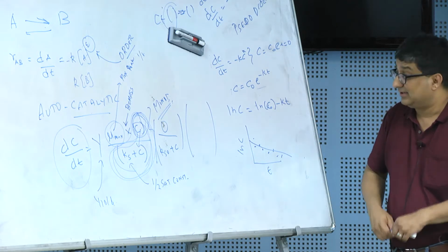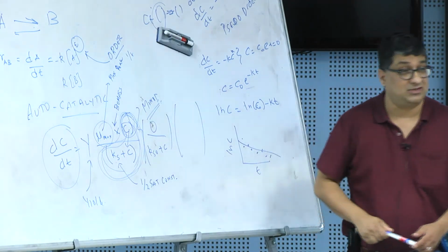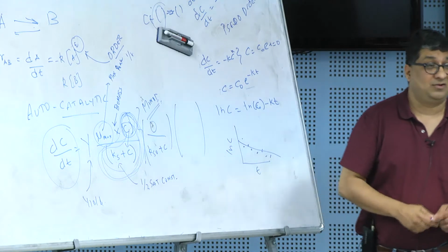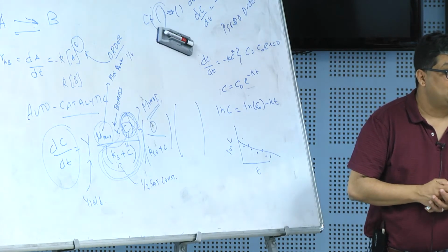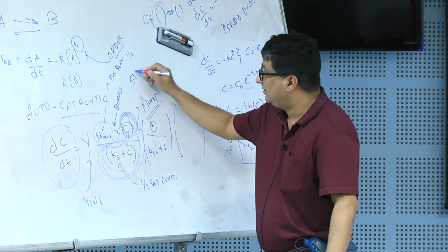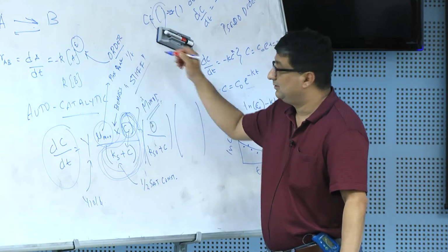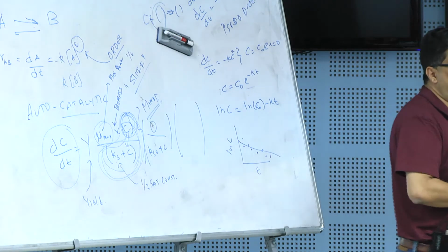The downside of it is there is concentration here, there is concentration here if we want to solve for concentration, so it's a highly nonlinear equation. And this is one of those equations that are called stiff equations. Okay. So when I was talking about differential equations, you see these big transients for certain concentration ranges. Suddenly the model starts to go crazy. Okay. So if we make our time steps too big, you will get some bizarre numbers, so you'll have to solve them at very, very small time steps when those transients happen.